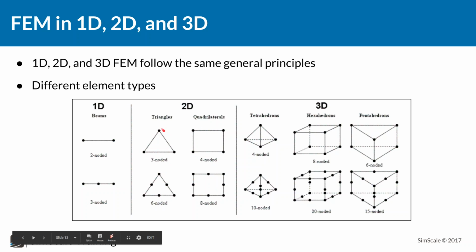So I can use the 3-noded or 6-noded elements. And if you think about it, using more nodes on one edge, what will it change? It will just change the resolution inside this element. So we will be able to interpolate with a higher order and a higher resolution between these nodes. Because actually, what the computer later is doing is only calculating what is happening at the nodes.